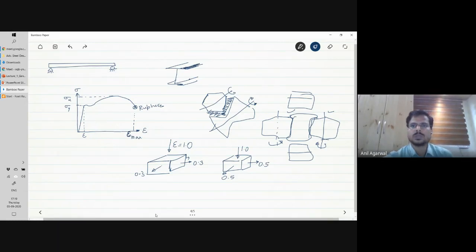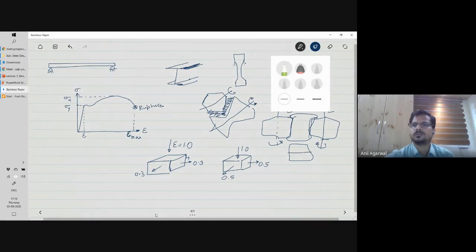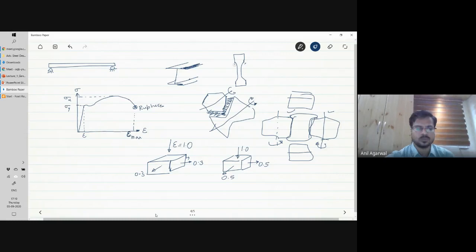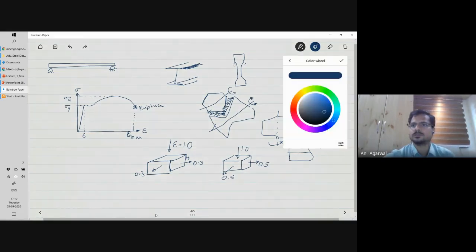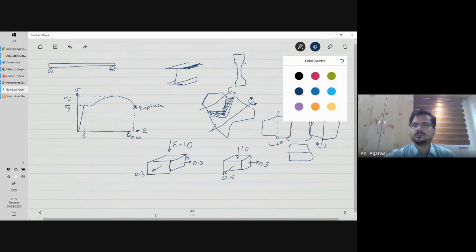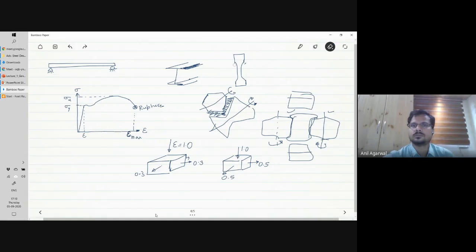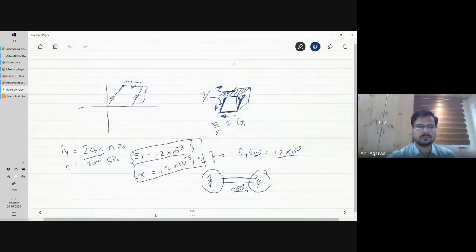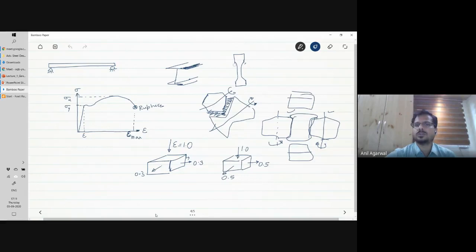That strip looks like this. It is a straight strip. I mean, I cannot draw it straight. So this is how the strip looks. Then we need to cut a dog bone shape on this one. Okay. This is not to proportion, of course. So we cut it into a dog bone shape. This is called a typical tension test coupon. Okay. And the requirements for the dimensions, etc., are given. Anyway, you get the point. So this is how a typical coupon looks.